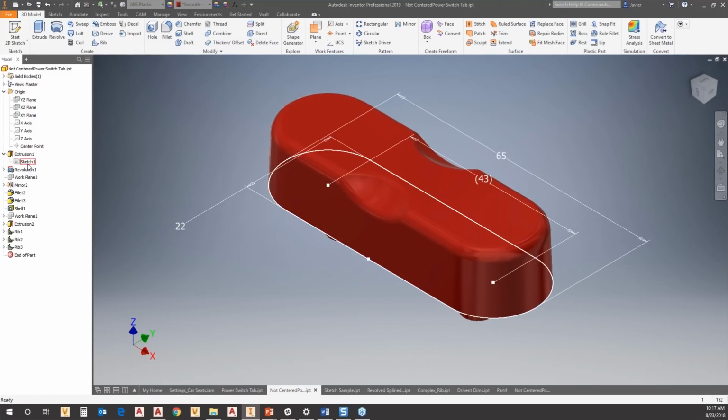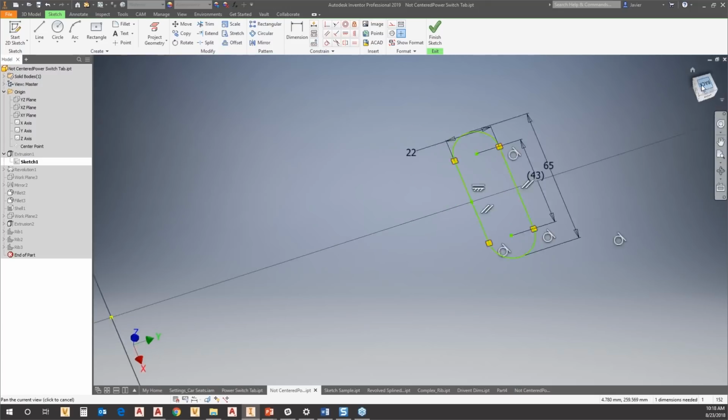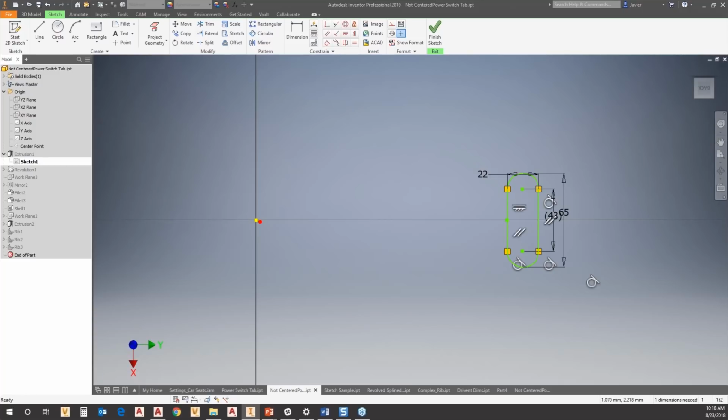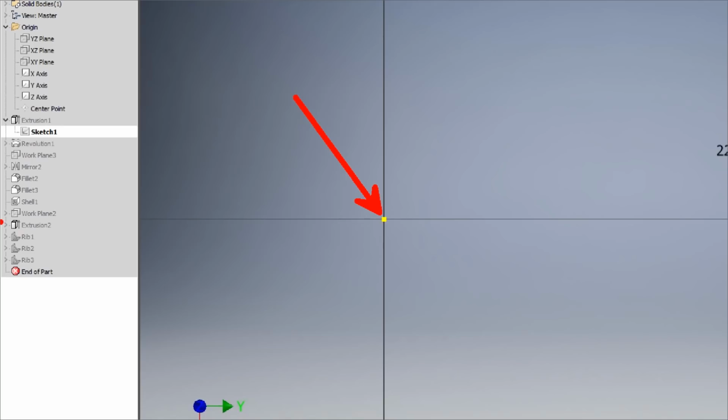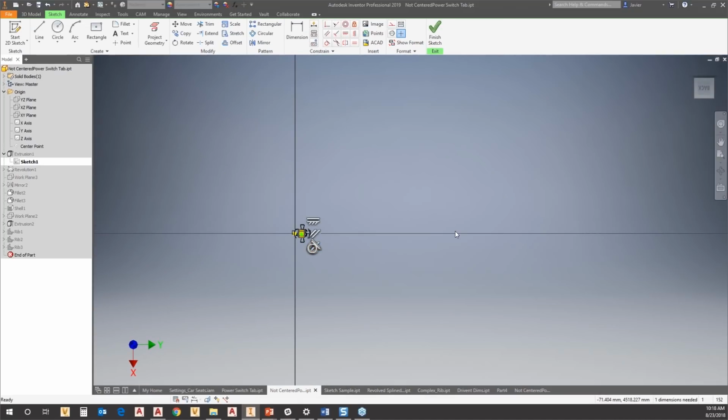every time you go to sketch on this or edit a sketch, almost every time, if I have my orientation set to look at the part, it'll do a sort of zoom extents and always zoom to 0. So if you can imagine, if this distance was like 100 feet, every time you would do a zoom all, it would zoom way out there, and you'd have geometry way out here.